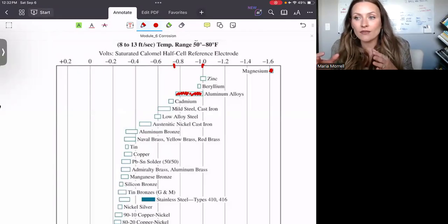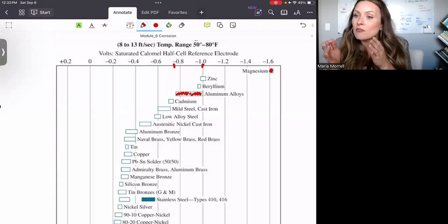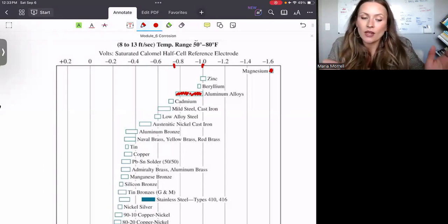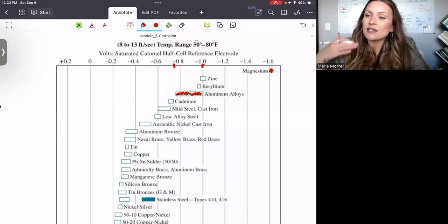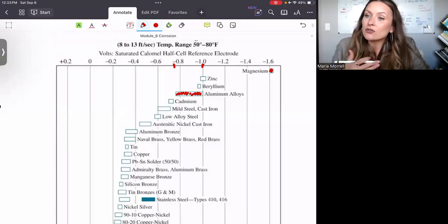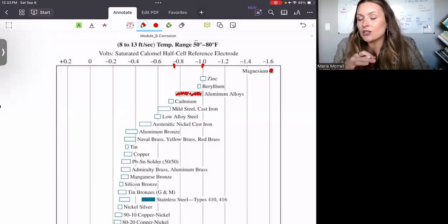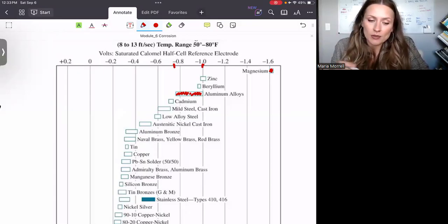So if I do not have the intention to corrode either of my materials, I would use this series to choose the metals that have similar potential to avoid the formation of a galvanic cell. Now, the reason I kept emphasizing that the galvanic series is generated experimentally is because it can show you the data that you want to predict, or perhaps you would predict the opposite.